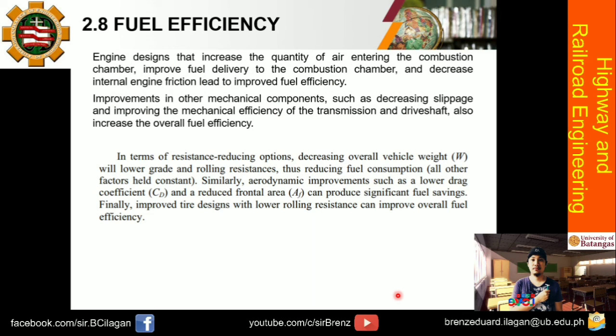Okay, so for fuel efficiency, the engine designs that increase the quantity of air entering the combustion chamber, improve the fuel delivery of the combustion chamber, and decrease the internal engine friction lead to improved fuel efficiency. Improvements in other mechanical components, such as decreasing slippage and improving the mechanical efficiency of the transmission and drive shaft, also increase the overall fuel efficiency.